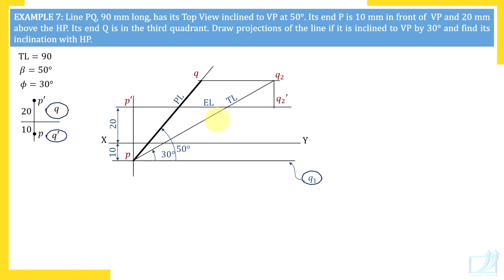Unless you are sure that there are horizontal and vertical lines through all labeled points, don't use the compass. So still there is no vertical line through Q. Now which other point is on this line? Q dash. Q dash is below the XY line, but there is no other line in our drawing on which Q dash is. So simply draw a vertical line and label it in this manner to remind us that this is the line on which Q dash is.